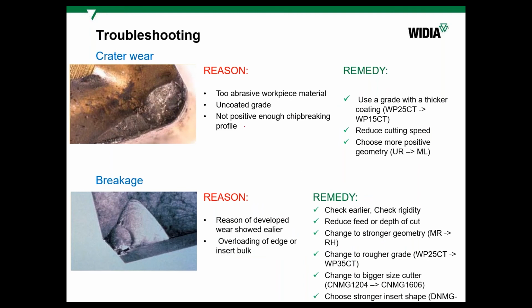Crater wear, it's not so easy to find such kind of wear today. Usually it's caused by too abrasive workpiece material, because the main contact during the chip evacuation is here, or especially if it's an uncoated grade, or not a positive chip breaking profile. So basically we need to choose a harder grade or reduce cutting speed or choose a more positive geometry in order to